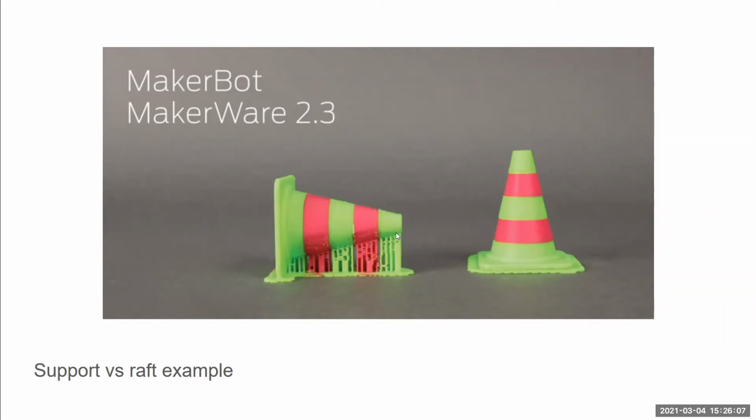But in order for this model to generate that corner, it needed something below it to bind onto. So there are ways that 3D slicers can create things called supports. What that support does is it looks ahead to where an object would otherwise be floating in the middle of thin air, and extrapolates from there down to the base of the print an idea of how to support that. So it generates these little supports, which are intended to be broken off or cut away and then discarded so that this model can be printed.